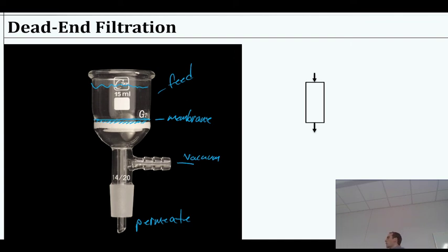Something interesting to note here is if we do use a vacuum for filtration, we have an inherent pressure limit. If we're using a vacuum, then the maximum pressure we can apply is 1 atmosphere, if we're doing this in a standard 1 atmosphere environment. We could go to Jupiter and have a much higher pressure if we pressurize the vacuum down to essentially 0. But on Earth, we typically have one atmosphere worth of pressure to work with, and that would be our pressure here.